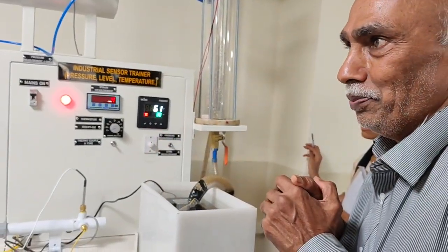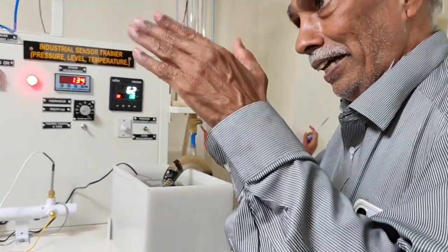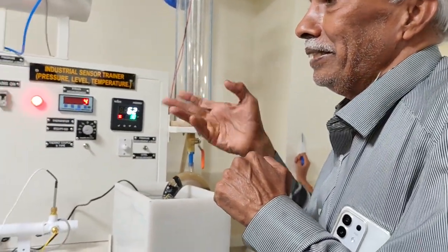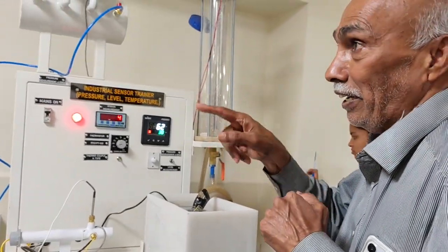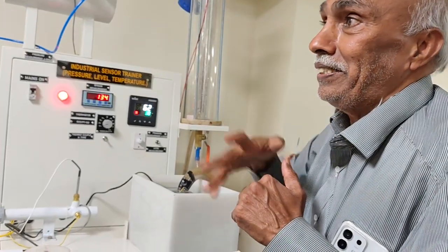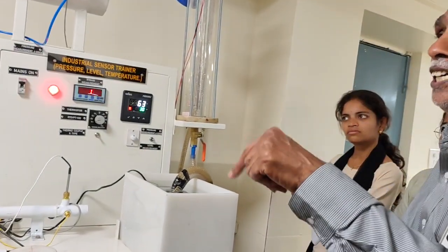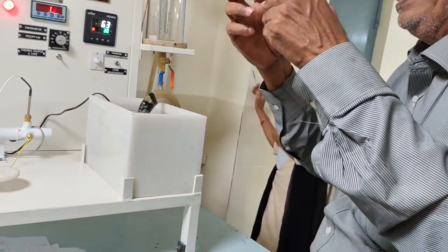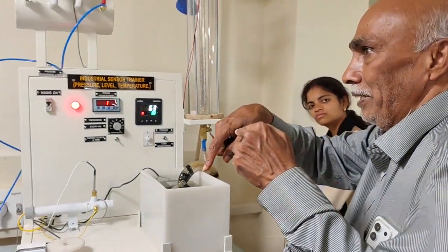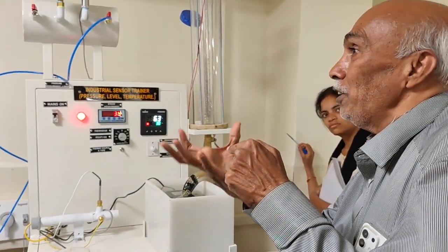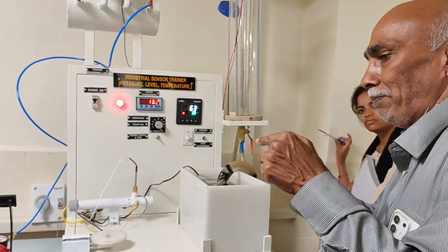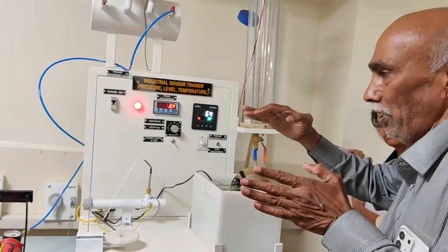It will go above. No, that was working, sir. The idea was not like that. His idea was different. It should cut off exactly at the set temperature, he is saying. That's what he is not able to understand. I told him, your sensor is in the chamber. The heater coil is there. Once it cuts off also, the heater coil will be red and keeps slowly cooling down. Unless the chamber temperature and heater coil temperature become equal, it will not cut off.